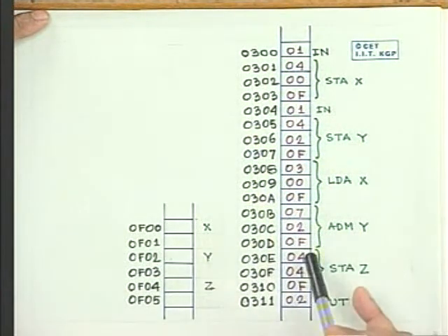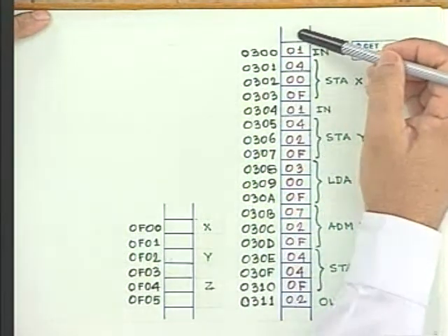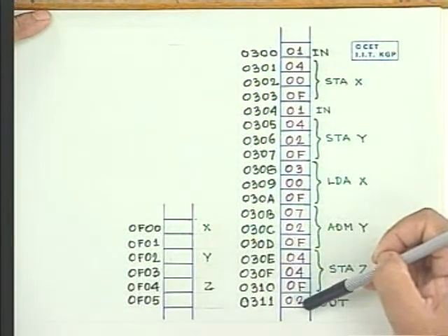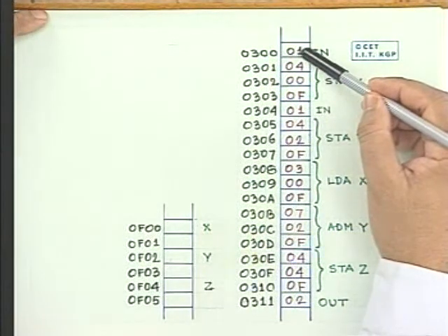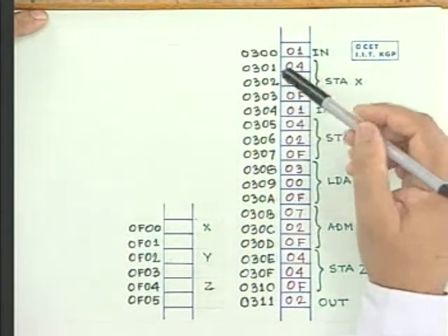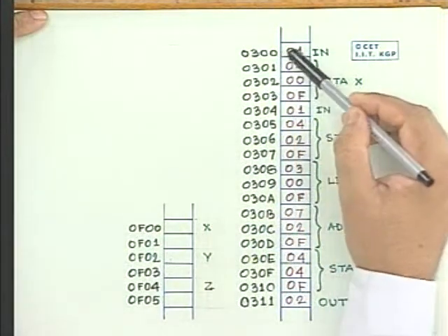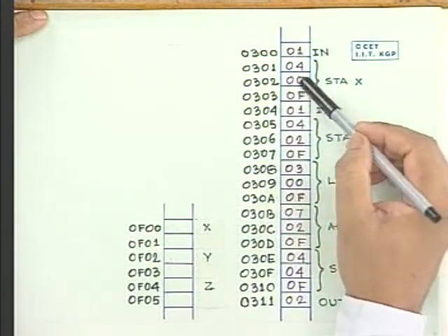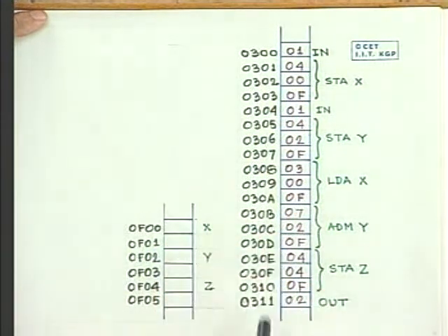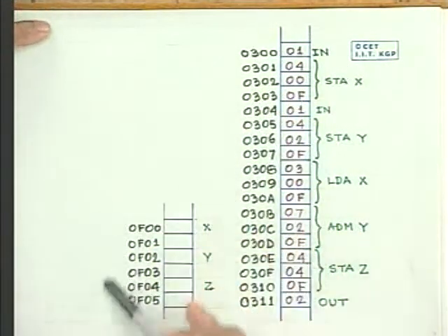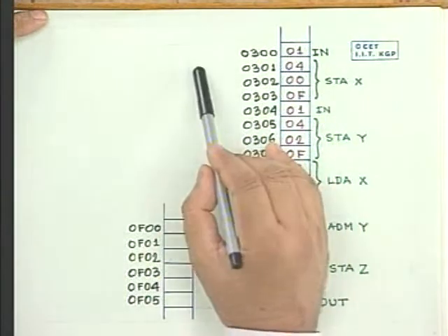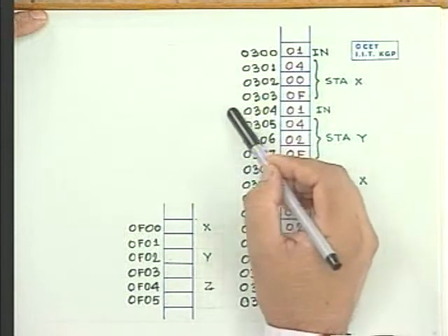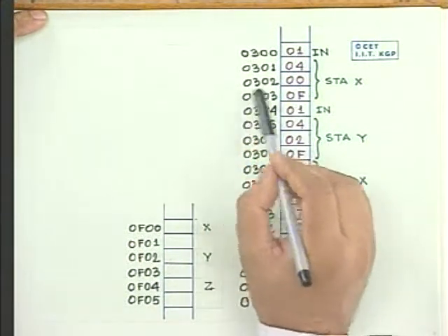Therefore, let me repeat that I am talking in terms of a memory which is byte oriented, in the sense every byte is addressable, but if we want, we can take out or push in either 1 byte or one word consisting of 2 consecutive bytes. That is the assumption I mean whenever I am talking about accessing the memory to take something out of it or to write something into it.